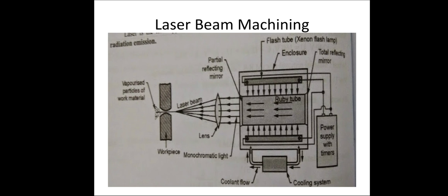First, place the workpiece on the table. As there is an absence of cutting force, fewer work holding devices are needed. The focal point of the laser is intentionally focused onto the surface of the workpiece for providing the heat in a concentrated manner. Due to the striking of the laser beam, heat is generated at the workpiece surface, and as a result the material vaporizes instantly, producing a cut in the material. The movement of the machine axis is through computer control, which helps to achieve the required profile of the workpiece.